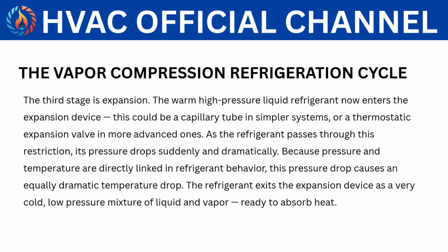The third stage is expansion. The warm, high-pressure liquid refrigerant now enters the expansion device. This could be a capillary tube in simpler systems, or a thermostatic expansion valve in more advanced ones. As the refrigerant passes through this restriction, its pressure drops suddenly and dramatically. Because pressure and temperature are directly linked in refrigerant behavior, this pressure drop causes an equally dramatic temperature drop. The refrigerant exits the expansion device as a very cold, low-pressure mixture of liquid and vapor, ready to absorb heat.